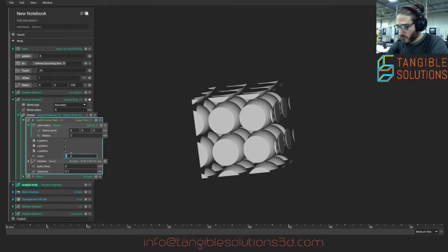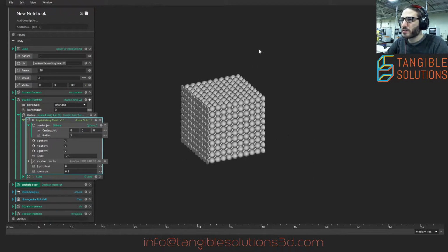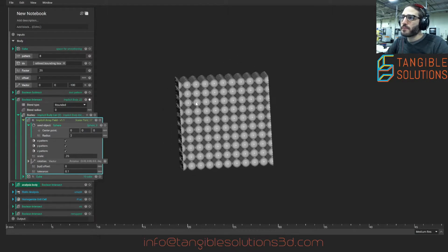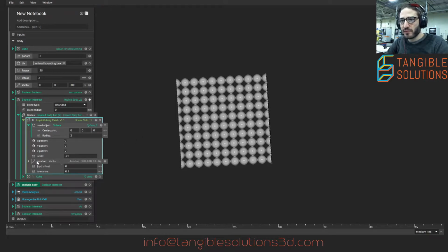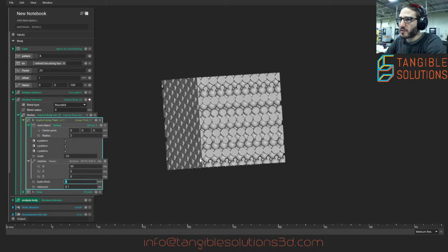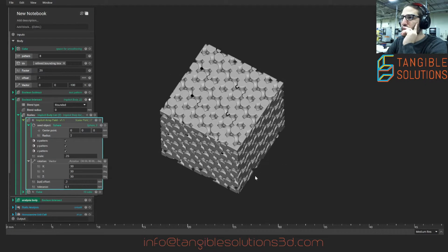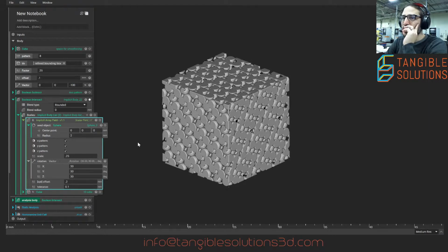There's lots of cool things about mod, but one of the cool things is it fills your design space inside nTopology infinitely, or at least as filled as you need it to be. And it's also really, really fast. So if I want to change some of the angles of the pattern, or do an additional offset of the body, you can create these really nice structures.